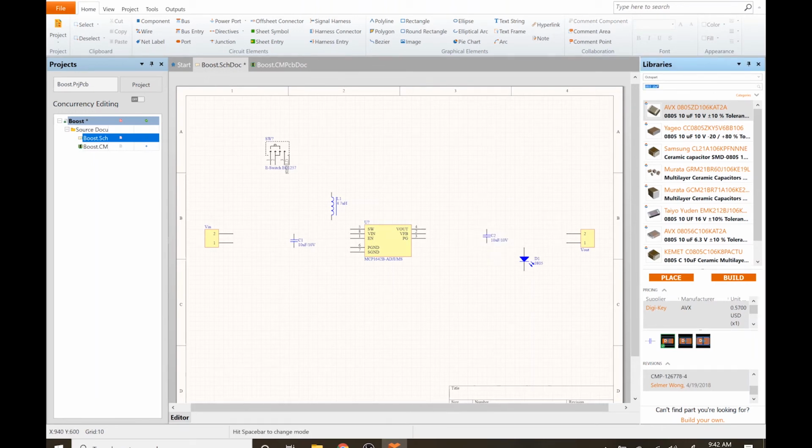And I'm also going to stick to 0805 size. So 0805 refers to the standard measurement. That's going to be 80 by 50 mils. That is the dimensions of the component. 1206, for example, would be 120 mils by 60 mils. So I want two resistors. I want a 680K.